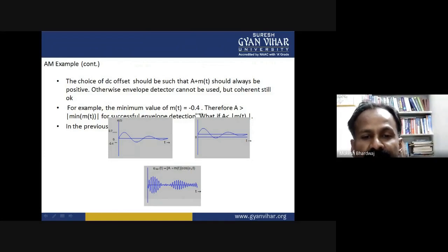Also, the carrier frequency is greater than the modulating frequency, and the signal which results from the process of modulation is known as the modulated signal. Modulation may be classified as continuous wave modulation and pulse modulation. If the carrier waveform is continuous in nature, then the modulation process is also called continuous wave modulation. Examples of this type are amplitude modulation and angle modulation.